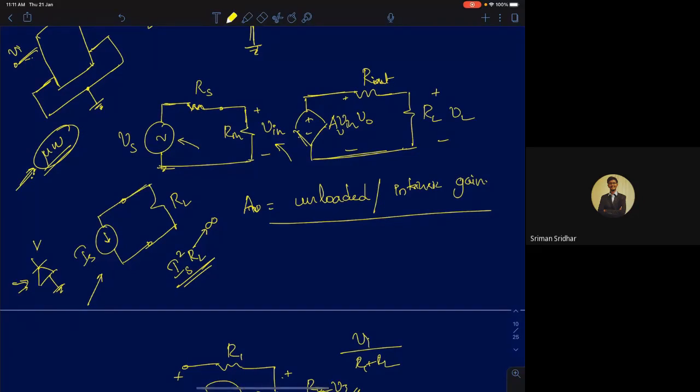To model that, one of you asked why not put a resistance in series. We said that doesn't make sense, because even if I put the resistor in series, the current flowing out through RL will always be IS. That's not going to change. So the power will always be I squared RL, and even though I'm modeling this with a series resistor, it really is not the right model. The other way is to model it in parallel: you have to put an equivalent source resistance RS in parallel.